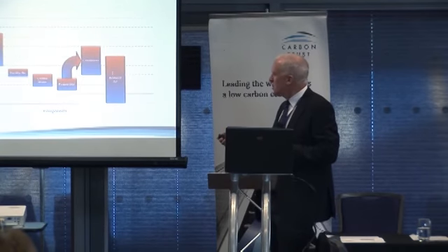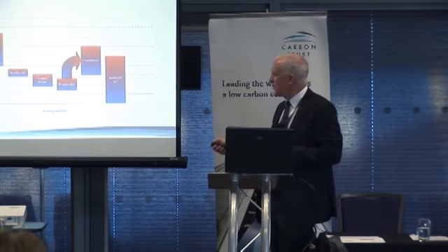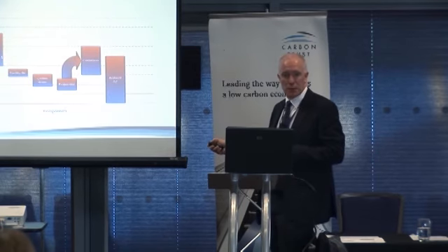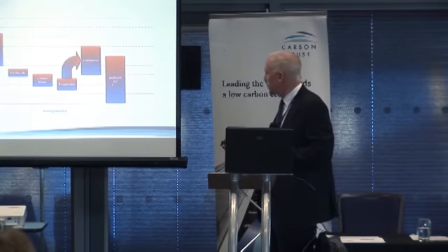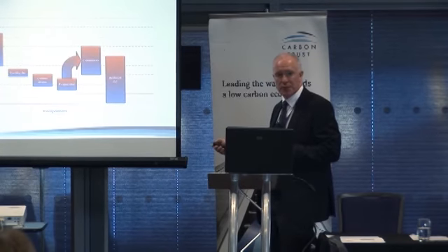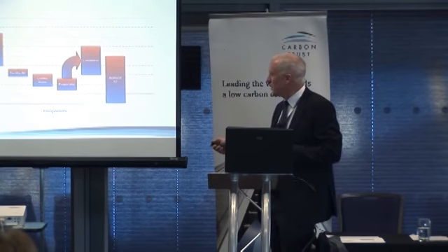So your typical ambient air during the winter, for example, is probably about 10 to 12 degrees centigrade, and is lower than the temperature of the chilled water you're likely to be operating at, and certainly much lower than facility air. Facility air 24 degrees centigrade, outside air 12 degrees centigrade on average during the winter. So this is more than enough during most of the year to give free cooling.